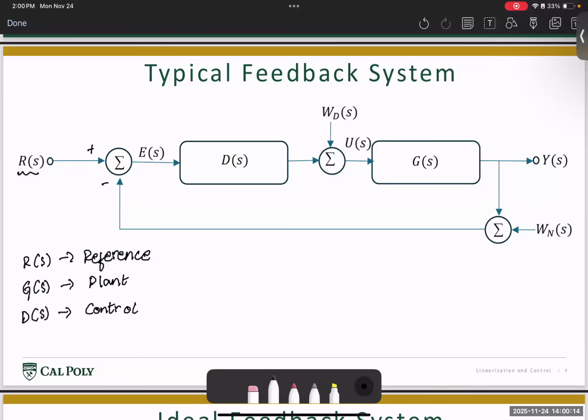All right, and then we have WD. We discussed WD to be some form of disturbance noise. This is usually caused within the system itself. As you provide a control input to the system, there can be some amount of noise that gets added, and we model this as disturbance noise. And then once the signal has been sent into the system, the aircraft would now start pitching. Then the output of the aircraft system Y is the actual pitch that we measure using different sensors on the aircraft. So this would be the output of the aircraft.